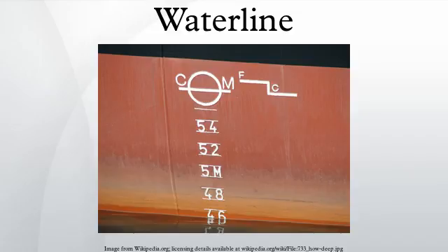The timber fresh and the tropical timber fresh load lines are calculated in a similar way to the freshwater and tropical freshwater load lines, except that the displacement used in the formula is that of the vessel at her summer timber load draft. If this cannot be ascertained, then these marks will be 1/48 of the timber summer draft above the timber summer and timber tropical marks respectively. The timber winter North Atlantic load line is at the same level as the winter North Atlantic load line.